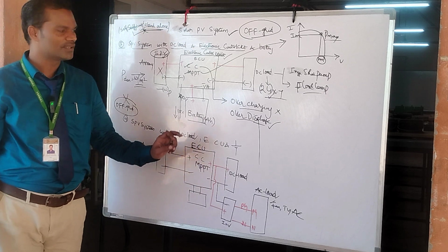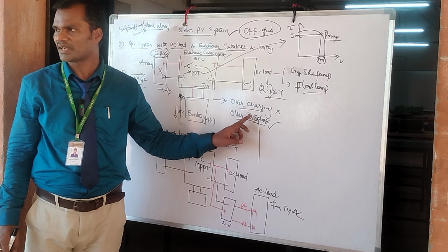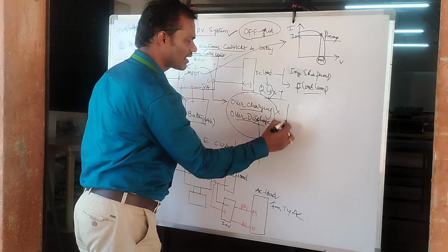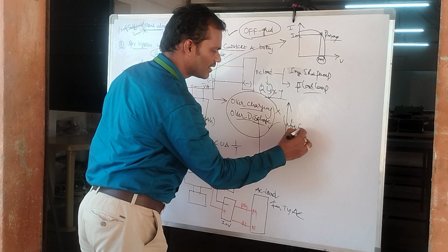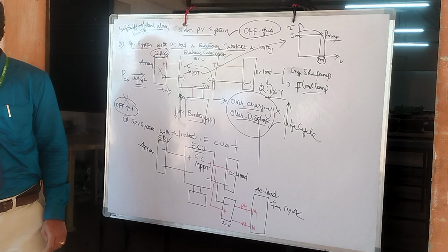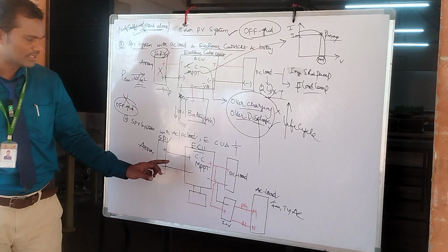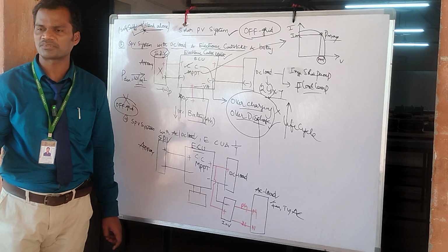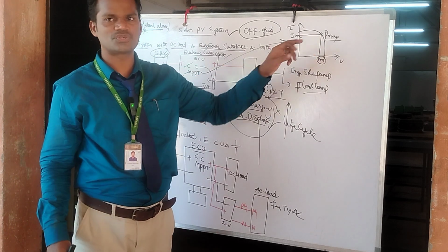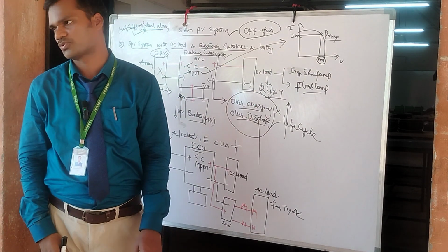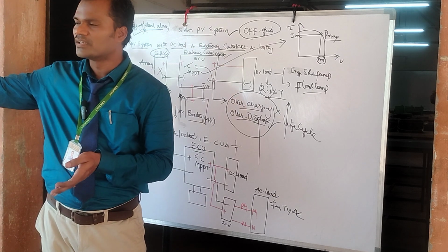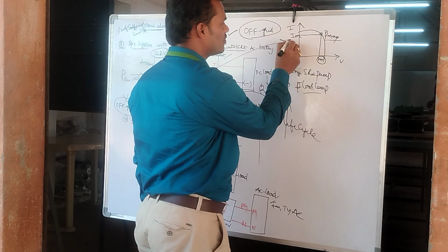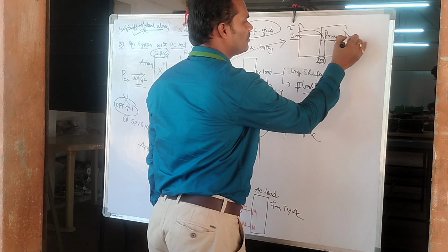Now, after the electronic control unit, if you have a DC load, the positive terminal and negative terminal are directly connected. Here on this DC load, you can operate a solar pump or a solar lamp. Some may not have that, because DC loads are very costly. We need to have which type of load? AC load, normal fan and normal tube light. Therefore, I am going to take a tapping at the positive terminal and at the negative terminal, and use a small micro inverter of around 1000 VA, a small 1 kilowatt inverter, to convert the DC supply to AC supply and connect it to the load. That load may be an AC tube light, AC charger or similar. In the DC load you can also connect your mobile phone. Why? Because the USB is there, no?